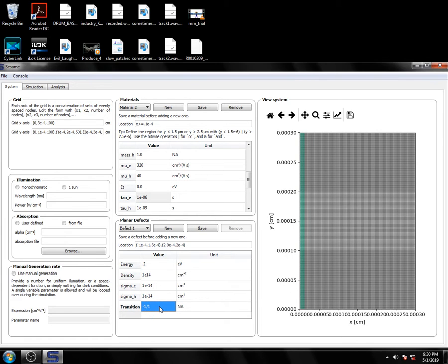So here, this is sort of like having a donor and acceptor defect state at this energy 0.2 above the intrinsic level. And so let's save that. And again, we see this depiction of a slightly tilted grain boundary in this N plus P junction here. In these regions, I can define the illumination and absorption of the material. Let's go ahead and choose one sun illumination.